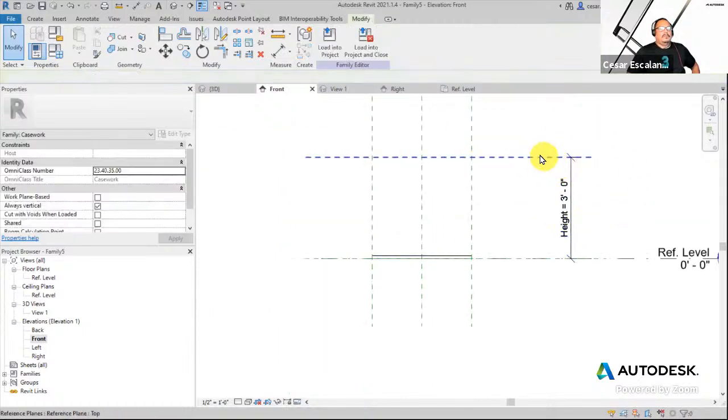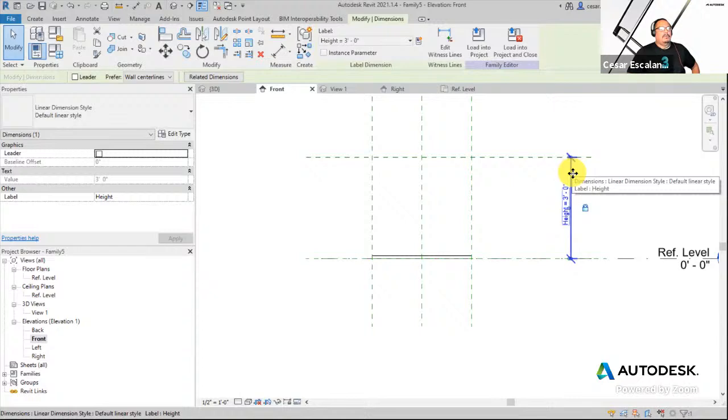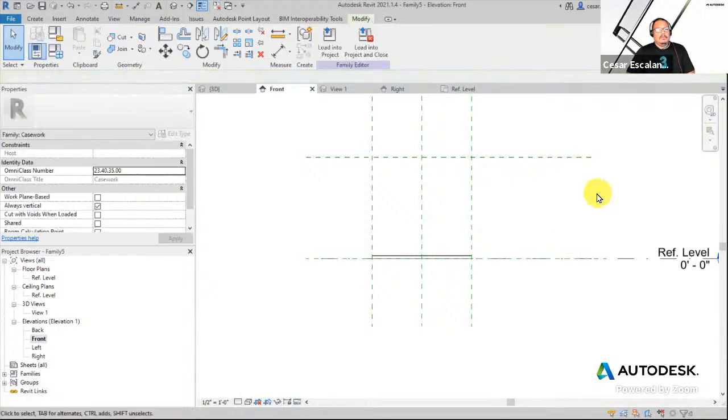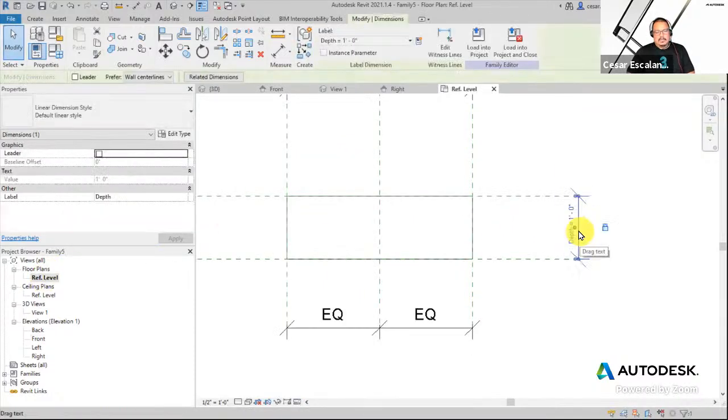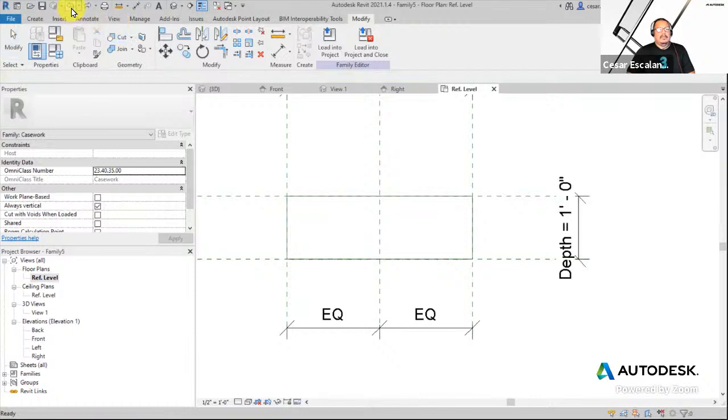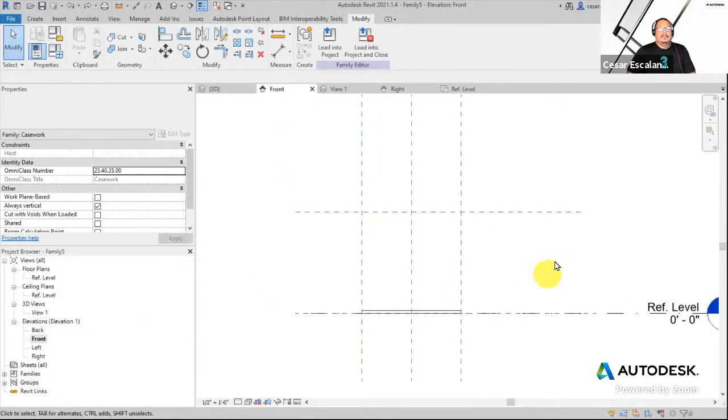This height parameter, which is defined in the template, is not going to be used, but this is a built-in parameter, and what that means is I cannot delete it. If you select this and hit it, oh, I could. I think it's the other ones. These guys, can I delete? Oh, yes, I can. It's in the other template that there are some parameters that cannot be deleted, but I deleted the height because it's not doing anything for me.